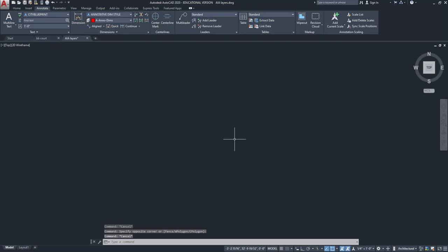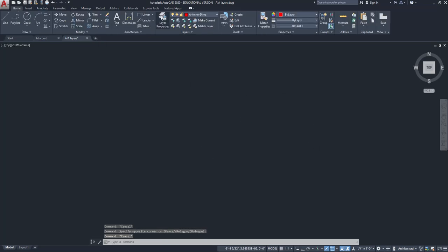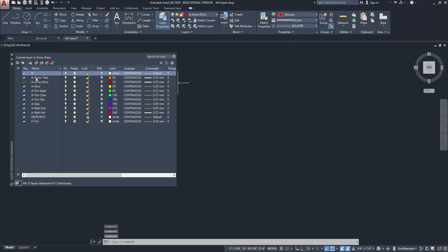All right, so this little point right here, if anybody was very curious about some AutoCAD fun, we'll say bits of information, you can see that little dot right there, okay? That little dot looks a lot like a defined point, and it is, but in actuality, that little dot right there is on the def points layer. It's built into the whole dimension structure, that point is the def points layer right there, okay? So when I taught you about layers and I said, hey, we have these layers and layer zero is for blocks, you create layers for different things, don't draw on def points, right? Because it doesn't print and it's used for something else in AutoCAD. Dimensions is actually what def points is used for, okay?